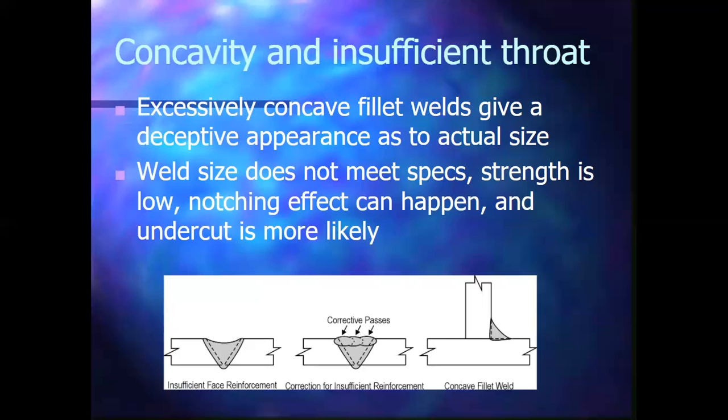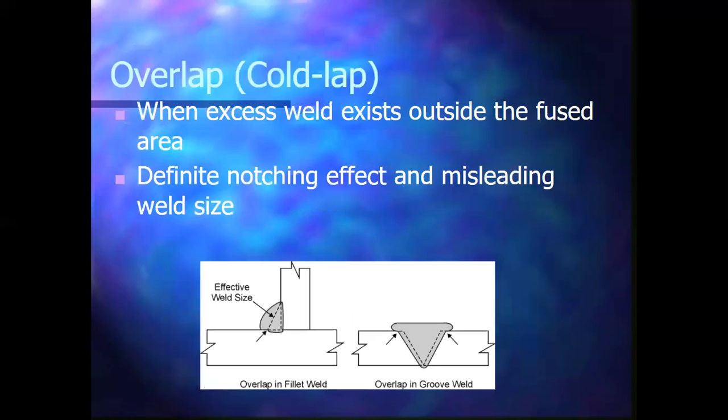This little excess that sticks out past here and past here doesn't matter. It's not included in the overall weld. That's basically extra weld you don't need. But if this weld was to be flat or even a little convex, we may be able to increase that dimension, say to 12 millimeters or whatever it is from 10. That's how measuring welding works. It's kind of a quick little demo. I don't hit it too hard in the 10 level. It's not that important for us right now.